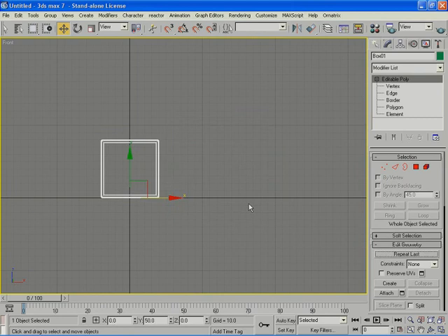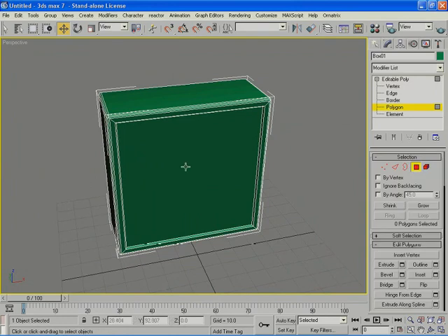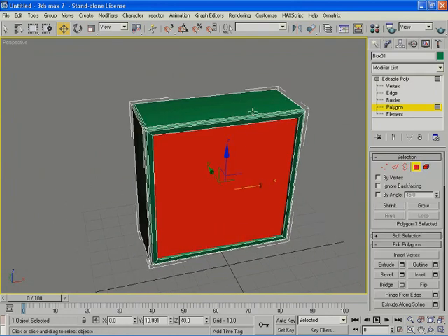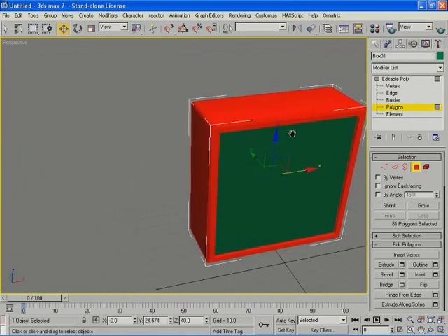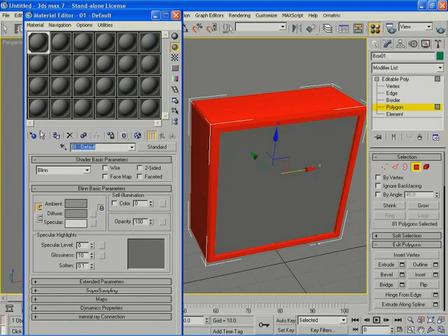I'm going to create a material for the plastic material for the parts outside the screen. So I'm going to select the screen and press Control I to select the rest of the polygons. And I will assign a material, call it black plastic. Okay, this is assigned. If I look here, I see those triangles around the material. This means that this has already been assigned, so I don't keep pressing assign all the time. It's not going to do anything. You just assign once, and whatever change you do is going to stick there.